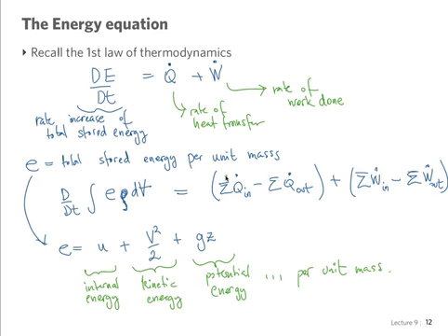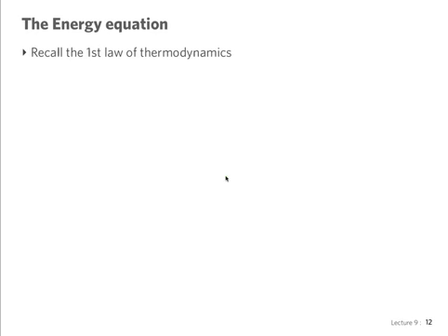I'm going to take a snapshot in case anybody has doubts, and clear these annotations and write again that I'm going to consider the change of energy net in a control volume as the partial with respect to time of the energy in the control volume, rho dV, plus the contributions of flux across any control surfaces.